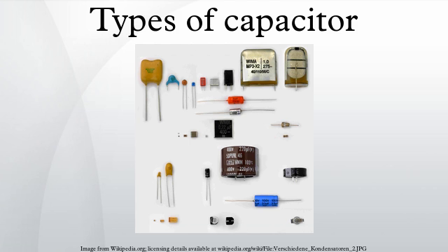A capacitor's summarized resistive losses may be specified either as ESR, as a dissipation factor, DF or tan δ, or as quality factor, depending on application requirements. Capacitors with higher ripple current loads, such as electrolytic capacitors, are specified with equivalent series resistance, ESR. ESR can be shown as an ohmic part in the above vector diagram. ESR values are specified in data sheets per individual type.